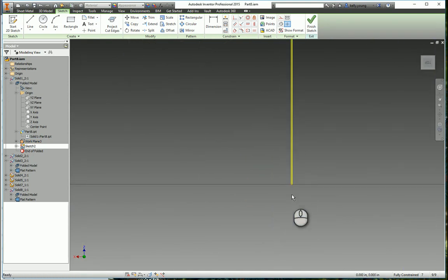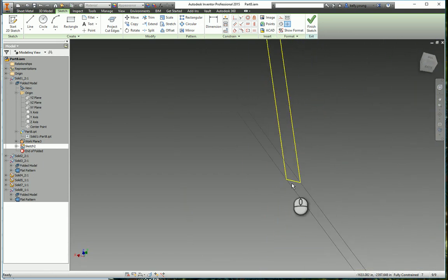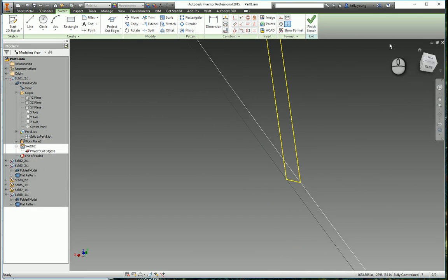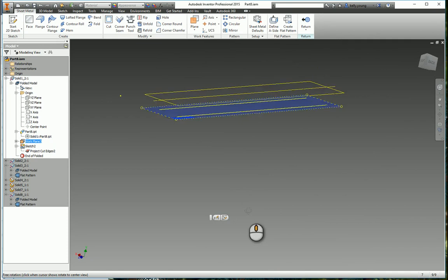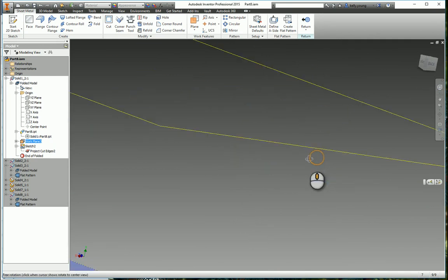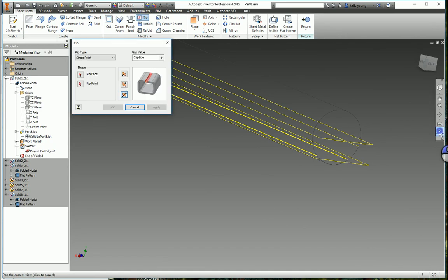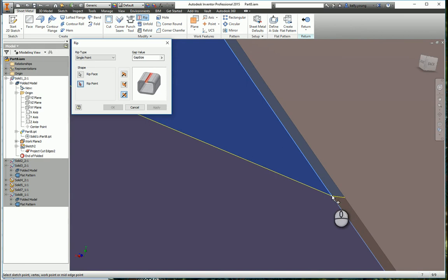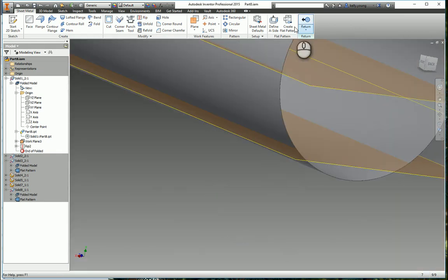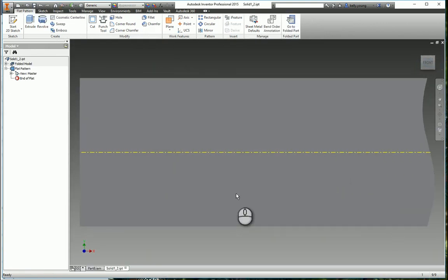Now you're going to have two lines because it's actually cutting through the thickness of this piece. That makes sense. So if we actually look at this, see, there's the two lines. Go to our rip tool. Let's turn on visibility. Select right there. So then it rips all the way through. Okay. Create a flat pattern. All right.